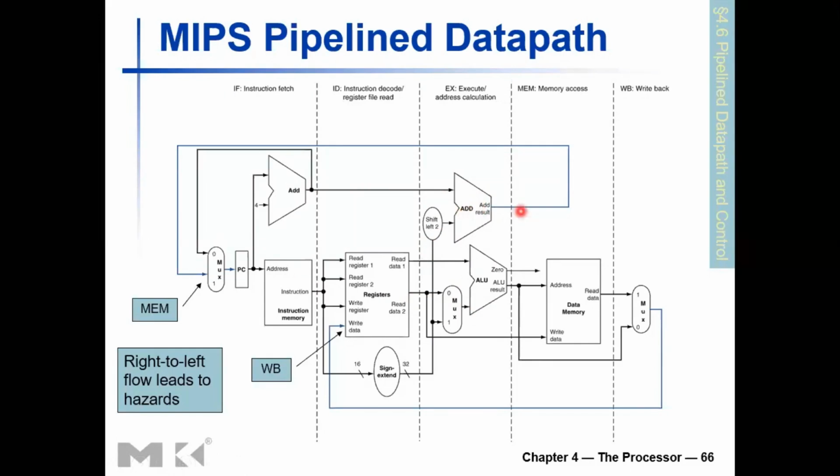And then in the memory access stage, the fourth stage, as the name implies, you do the memory access. You can read the memory for an address computed in the ALU or the execution stage. The address can be computed in the execution stage by the ALU, and you use that address to access the memory, either to read or write.